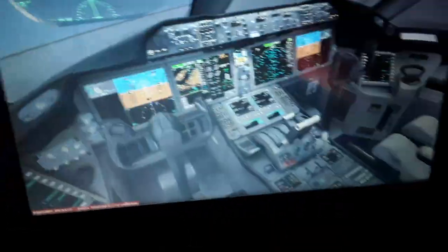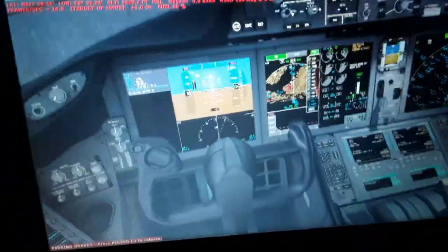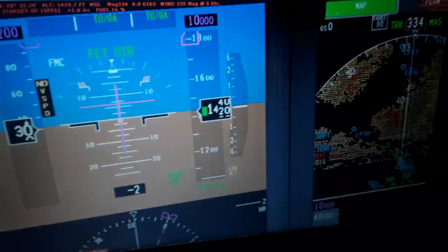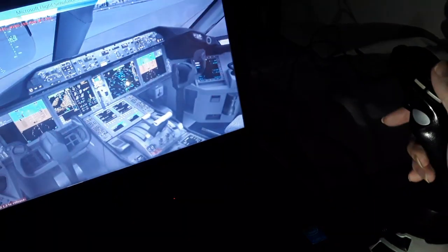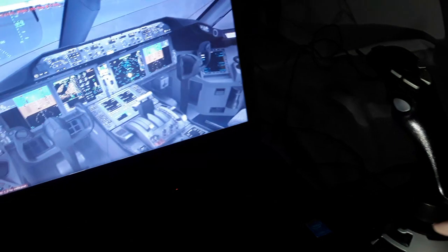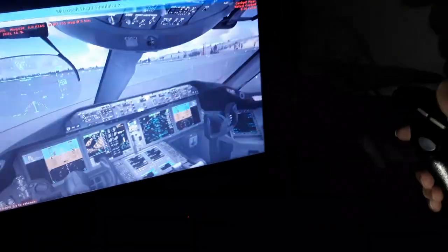You see the primary flight display where we have the airspeed indicated in the airspeed tape. We have also the stall speed displayed with a number and rate indication, so we need to avoid the stall when we fly. We press the yoke down or the side stick. If we are in the Airbus aircraft, we have the side stick instead of the yoke to control. So all controls the same, and then apply some thrust as needed.